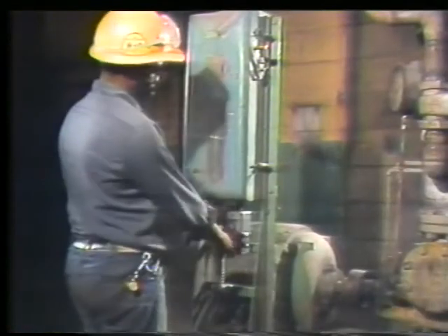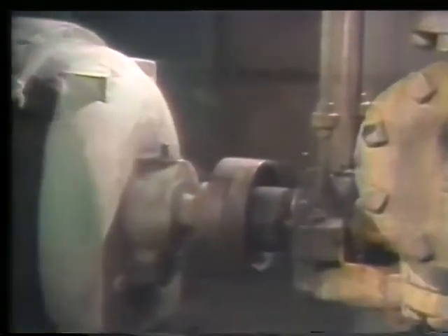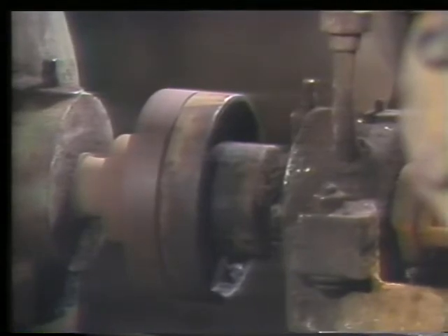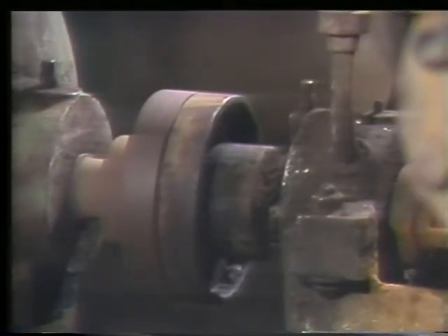Now, test the motor by turning it on briefly. This is called jogging the motor. By doing this, you'll be able to see if the motor is turning in the right direction and that it is indeed operating correctly.